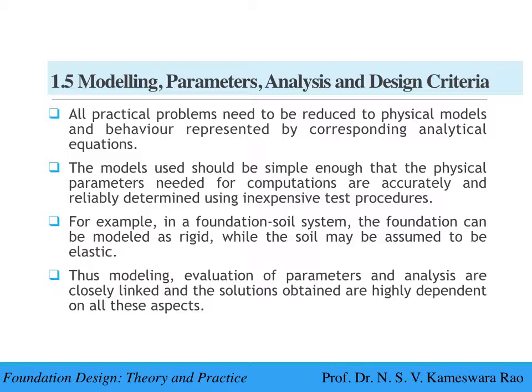The physical parameters needed in such a model are the elasticity parameters of the soil, that is, Young's modulus of elasticity, E and Poisson's ratio, ν of soil. Naturally, E and ν have to be accurately determined for the soil under consideration as they will be needed for the computation of the responses of the system.